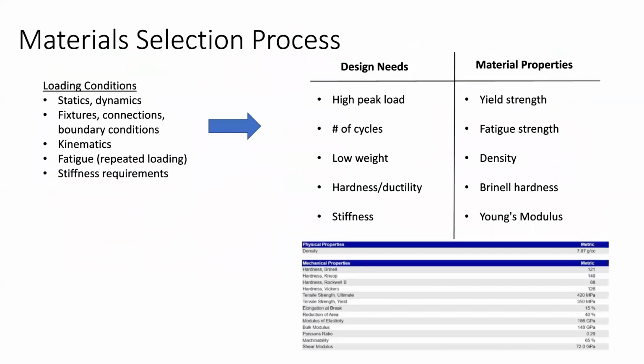Because that's a somewhat unintuitive requirement, but it relates back to hardness, which isn't something you would think about. So if you're doing center locks, the two really sensitive things are that the thread at the end that you're locking onto is loaded extremely highly axially from your preload. You need to push the system together with a lot of proof load. But at the same time, you also have the axial load from the tire going through the thread. And all of this is concentrated on that thread. So it's a lot more complicated because now you actually have moment loads on the thread as well, because part of how the load transmits from the tire to the hub goes through it. So it's that thread interface which basically dictates the material selection for center locks.